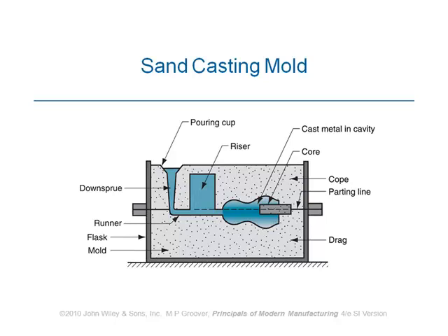We have the still molten material here, but this section which connects these two bits to one another is solid. What happens? Exactly. Those cavities or bubbles inside the part cannot be filled in. So then we've got to design this bit of the gate mechanism in a way that it does not solidify before the tube. How do we deal with this?